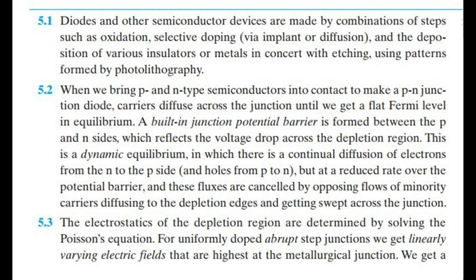5.1 Diodes and other semiconductor devices are made by combinations of steps such as oxidation, selective doping via implant or diffusion, and the deposition of various insulators or metals in concert with etching, using patterns formed by photolithography.